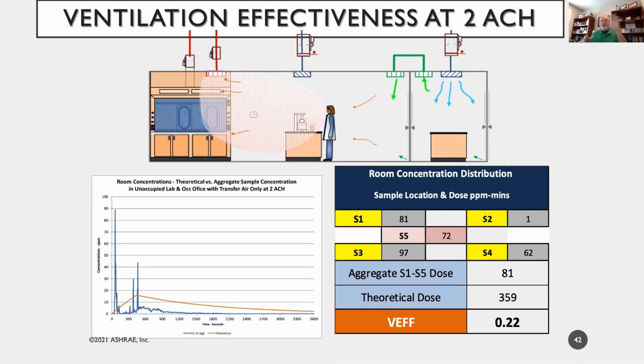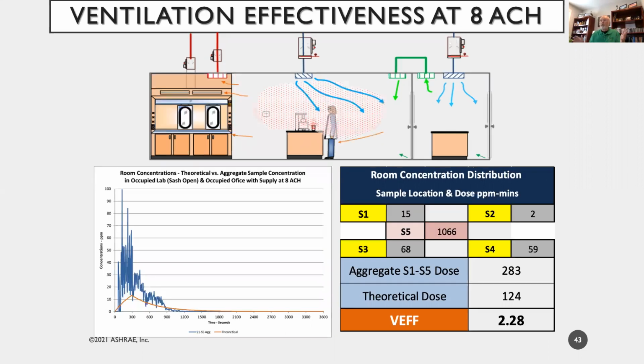You know, if you're walking by outdoors, you've got all kinds of ventilation. There's not much of anything in the air. But if you're in an enclosed room and the air is moving around as the engineer designed it to do, or maybe intentionally or unintentionally designed it to do, what is it doing? Okay, in this case, the 2 air changes is going away. So if we take this same design, which had the capability in this system to crank it up to 8 air changes, what happens? Well, it puts more air in the room.